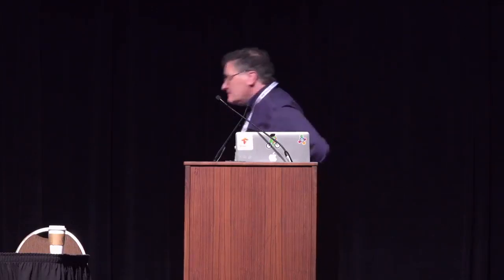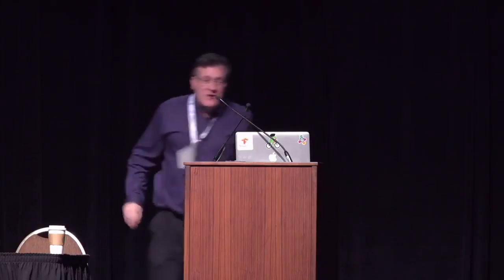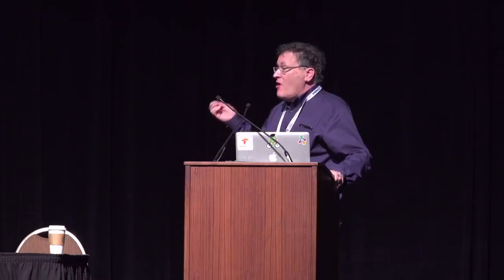What about geothermal? Okay. So the question was, what about geothermal? Geothermal is great, but it's only cost effective in what they call hydrothermal areas, in other words, areas that already have a lot of water passing through them. There's something called dry rock geothermal, where you actually inject water down, and there's been some work on it, but the trouble is the economics just don't work out. It'll be roughly as expensive as today's nuclear power, which is very uncompetitive.